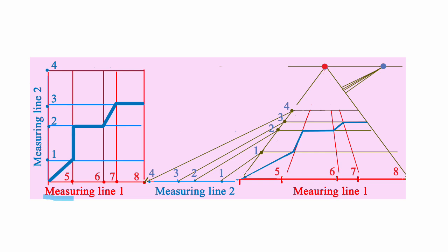In this situation, I established 2 measuring lines with units that help me draw this particular design. Then I drew my trapezoid, and I had measuring line 1 on the bottom here with lines converging toward the vanishing point. And I put measuring line 2 over here and drew converging lines to a vanishing point on eye level.